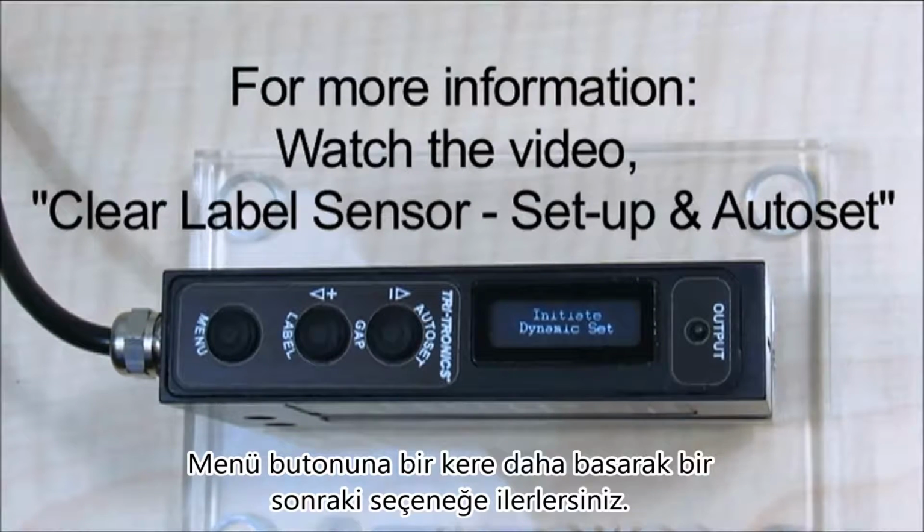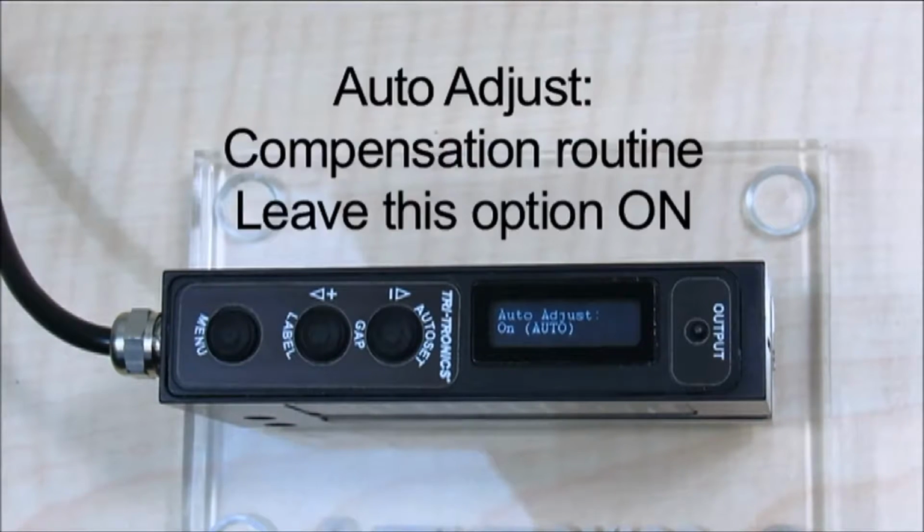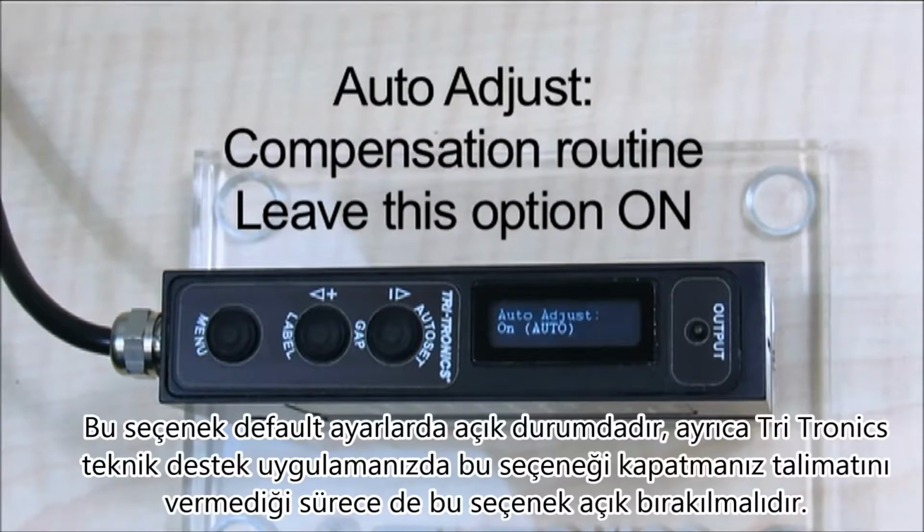Tapping the menu button again will advance you to the next option. In this case, the second option, Auto Adjust. The Auto Adjust option engages a compensation routine that automatically adjusts for small changes in signal levels between the gap and the label over time. This option is on by default and should be left on unless instructed by Tri-Tronics tech support to turn it off in your application.